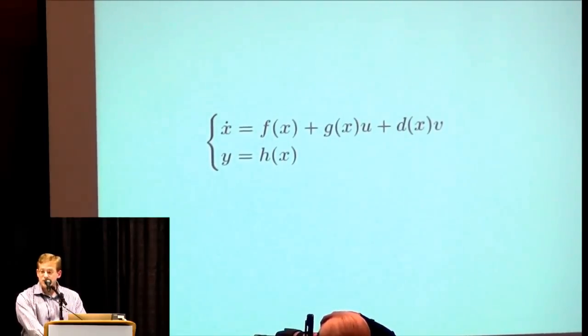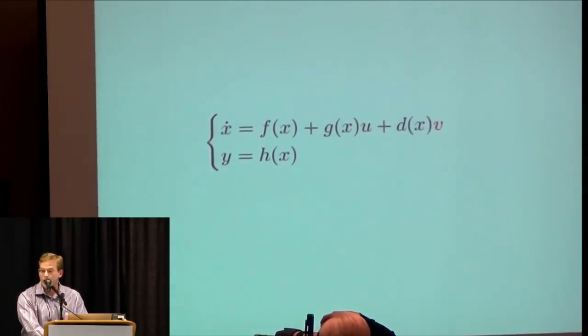Unfortunately, the inertial sensor biases v are unknown and must be identified. It's customary to include these in the state and to model their derivatives as noise. But while bias rates are small, they're not uninformative of the state. They're deterministically related, in fact, and so we can't simply omit them from the analysis.